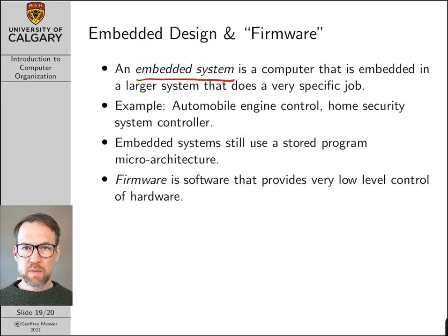These microcontrollers, in theory, could be programmed to do anything at all, but then we put them inside an engine and we connect the microcontroller to fuel injector controllers and sensors in the car. While in theory we could reprogram that microcontroller to do something that isn't car related, it doesn't really make sense because the thing is literally buried into a car and is only connected to automobile parts. And so that's what we refer to as an embedded design.